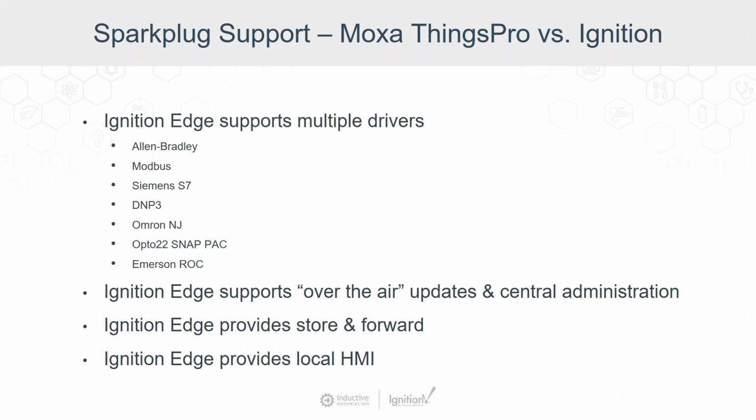One note that I want to mention here about MQTT is that Moxa's equipment, actually, with ThingsPro, supports MQTT Sparkplug natively, and they have a Modbus driver there, and a lot of these different equipments will support Sparkplug natively. And if it's a PLC or sensor that supports MQTT, perfect, because then there's no need for any edge gateways like Ignition to poll and to do those protocol conversions. It already supports it at the edge of the network.